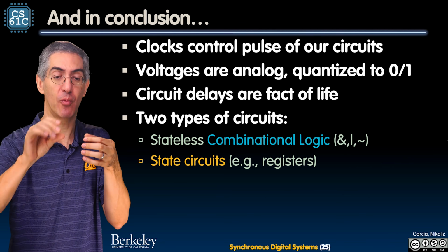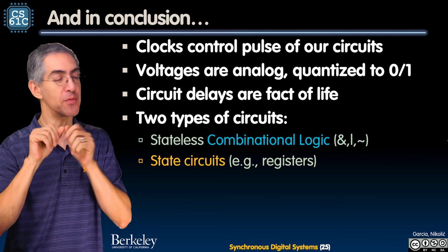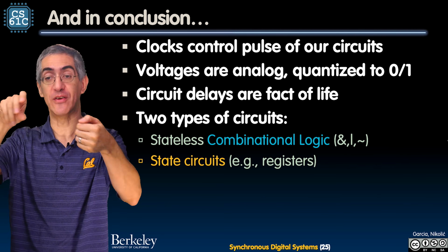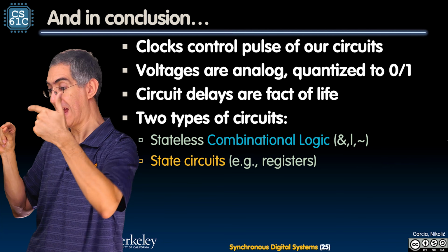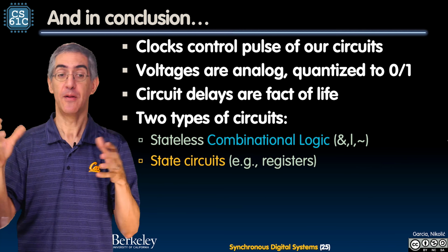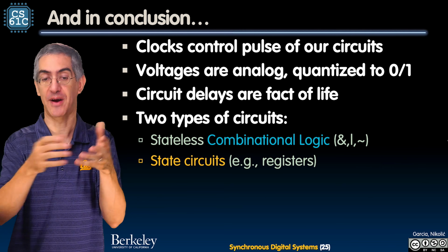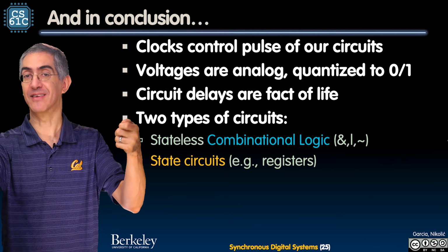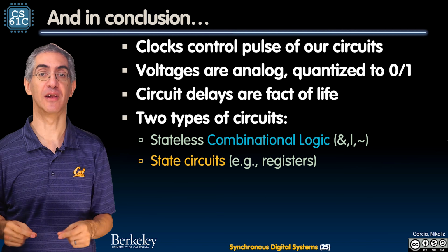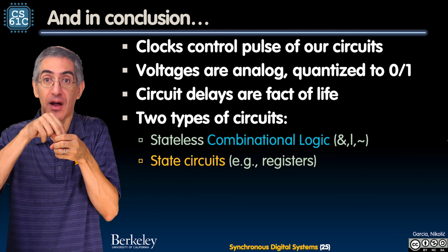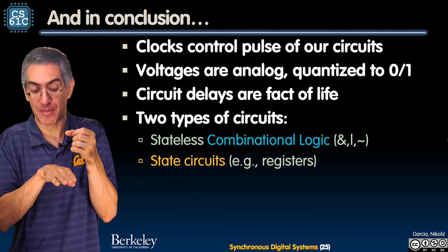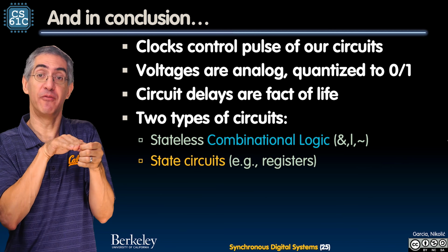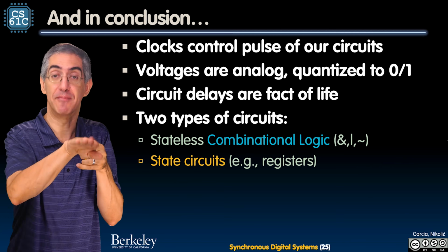And the only reason it would not be 3 is noise, or maybe there's some resistance on the line, so it had to go from here to here, and it started at 3, and it was lower by the time it got there. So the real world is going to influence this by adding noise to our system or having a distance with resistance across the line. But every one of our core blocks is going to try to clean the circuit up. If it came off a little bit higher than 0, we're going to clamp it down to 0. If it came in a little bit lower than 3, or a little above 3, we're going to clamp it at 3.